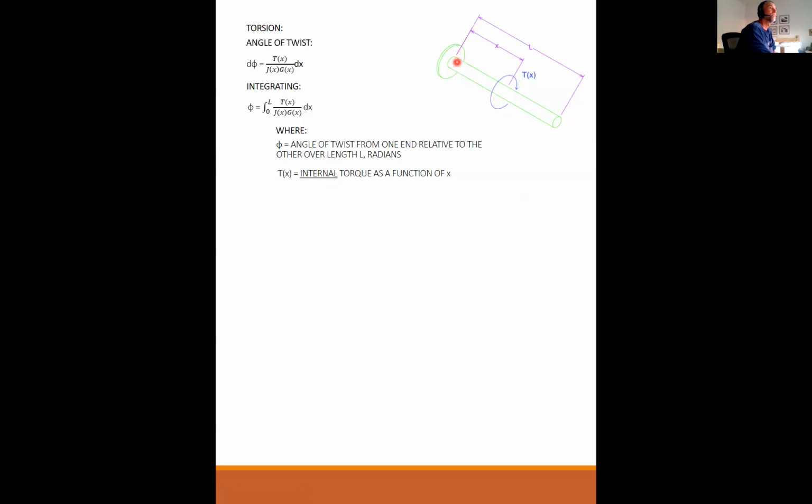What if this is a 2-inch diameter rod that skinnies down to a 1/2-inch diameter rod? This way we have to integrate. Yeah, but in the image I see everything is constant. In that image, absolutely, yes. But this is the general form, because you may get a situation where any one of these three is not constant.